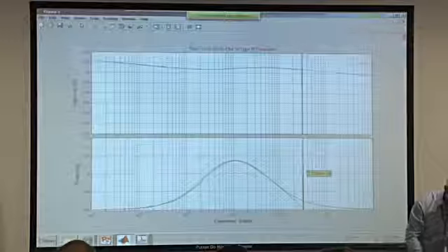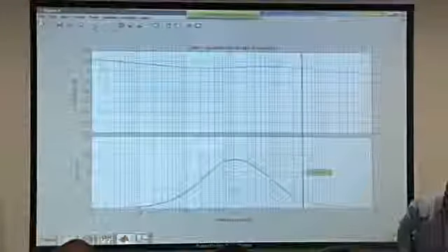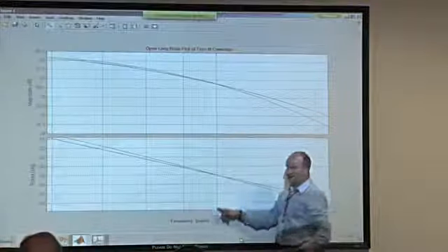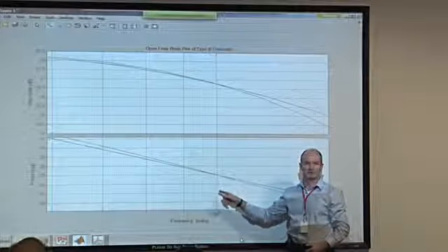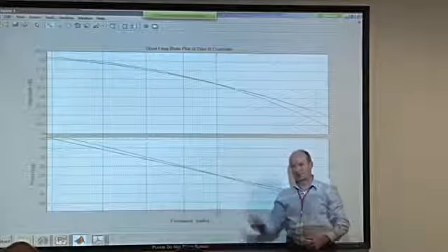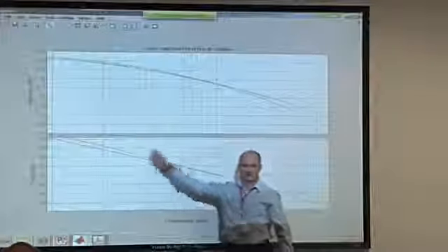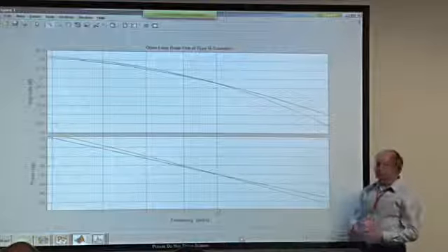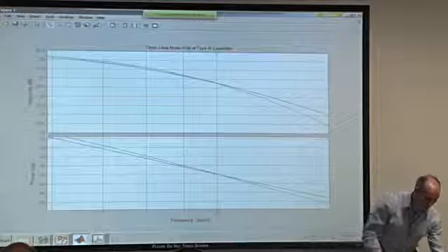well, that's what you get. That's a very, very small number. Well, let's call it 0, shall we, between friends? But if we zoom in on the frequency at which we've been measuring, we'll find that these 2 plots cross over exactly at 10 to the 6 radians per second because that frequency has been preserved by pre-warping. It's exact. But the price of doing that is that we've introduced a little bit of daylight further down in the frequency response. So it comes with a cost, but it does at least preserve specific frequencies in the frequency domain. It's called pre-warping.